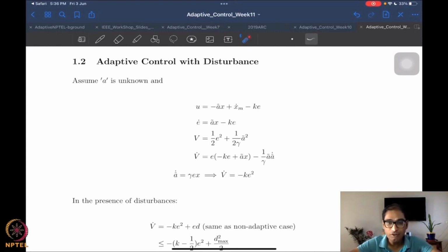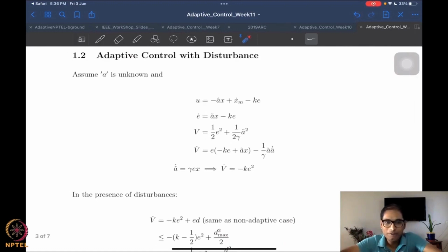Well, it can be strict if you have persistence of excitation and all that nice stuff. Then you can create some strict Lyapunov function for an adaptive control problem. But more often than not, that's not the case. That's why adaptive control theorists do not care about parameter convergence, because persistence may not be guaranteed. Therefore, you do not have strict Lyapunov functions, at least not in the setup that we have usually seen. Okay, great. So let's work this out and look at what happens.